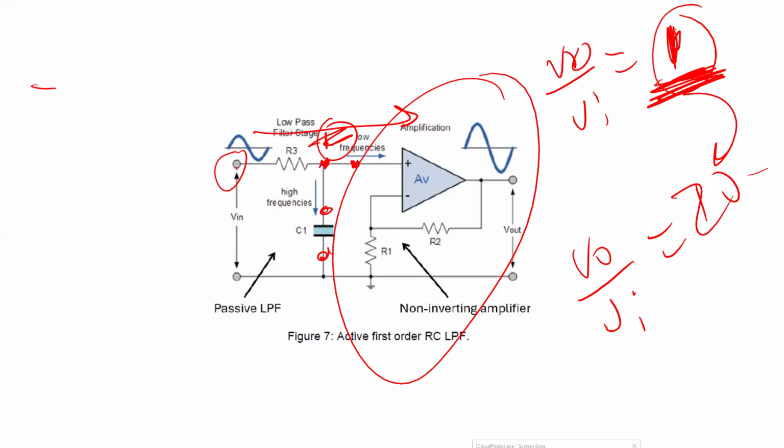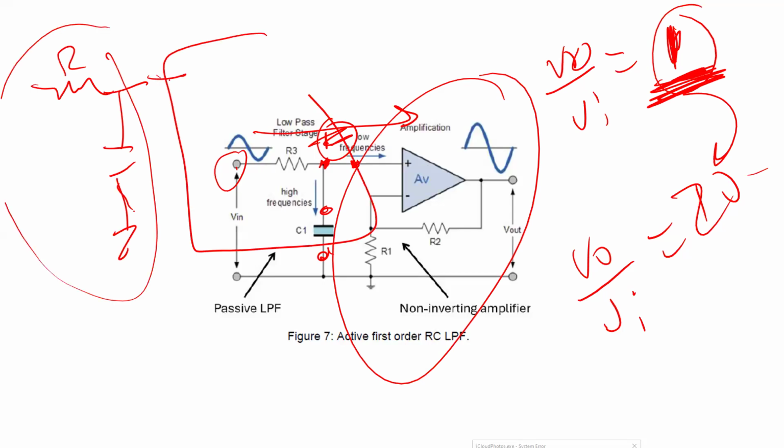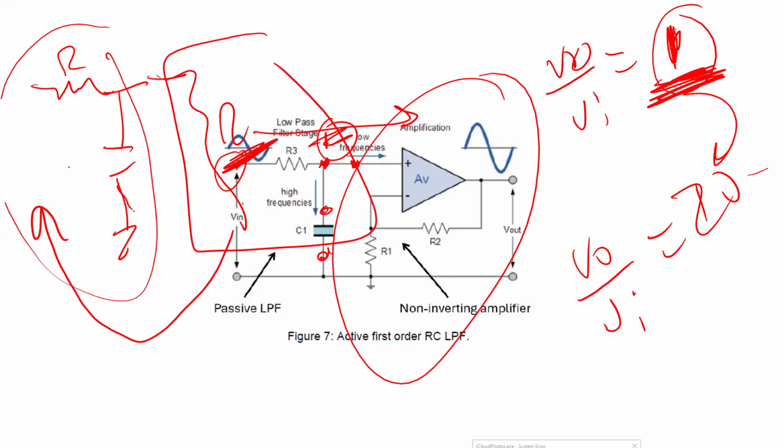Look here, if you have R and then a capacitor this way, for sure I'm not going to use this circuit alone. There is another circuit here. The circuit also has a resistance. This resistance is going to be a load. You are going to load the filter, and then you are going to change the cutoff frequency because it's like you added a resistance to the R and C. You see what I'm saying?